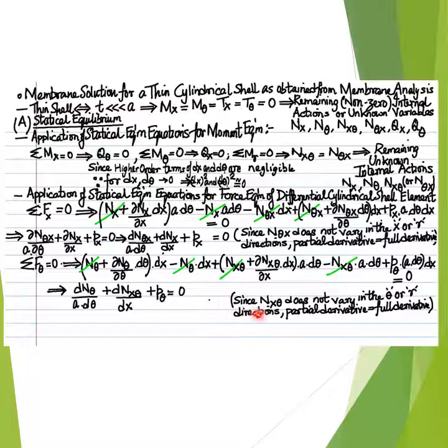and noting that the in-plane or membrane shear force nx theta does not vary in the circumferential direction theta or the radial direction r of the selected cylindrical coordinate system, the partial derivative of the in-plane or membrane shear force nx theta is equal to the full derivative of the in-plane or membrane shear force nx theta.